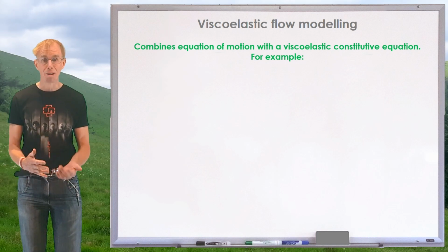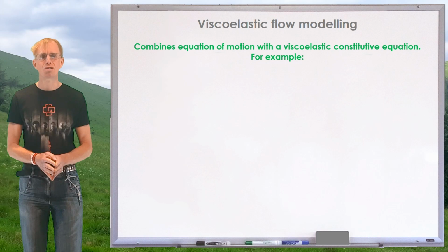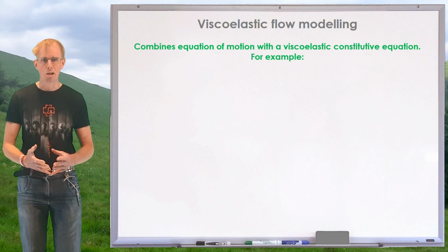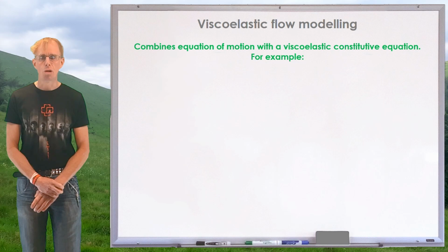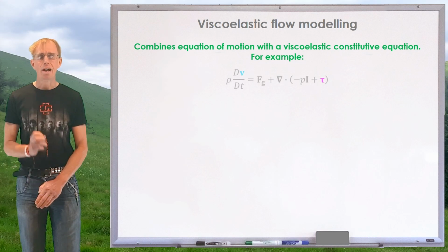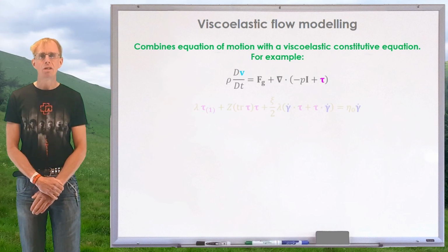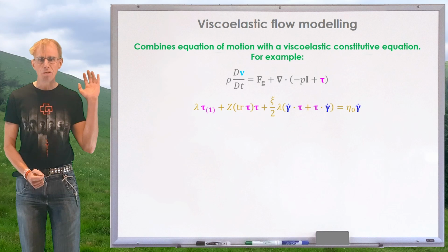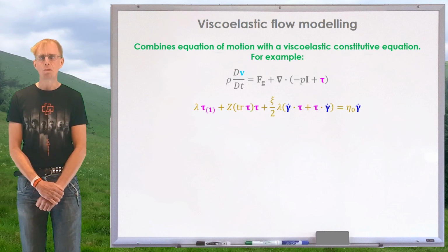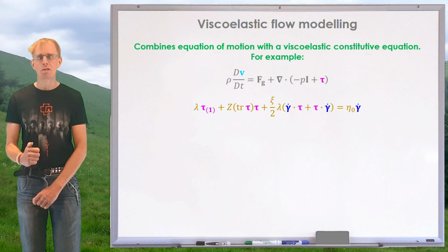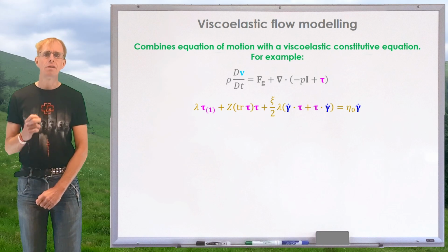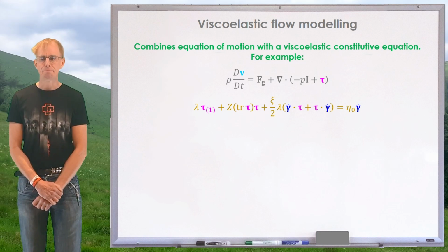Now, since we're talking polymers, that constitutive equation is no longer nice and simple like a Newtonian or a generalized Newtonian, it's viscoelastic. So what we need as one of our ingredients is an equation of momentum. So there's Cauchy's momentum equation there on the board. And I've highlighted two terms in that. I've highlighted the velocity term in light blue, and I've highlighted the stress term in pink.